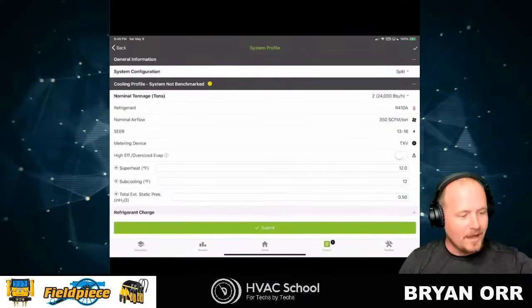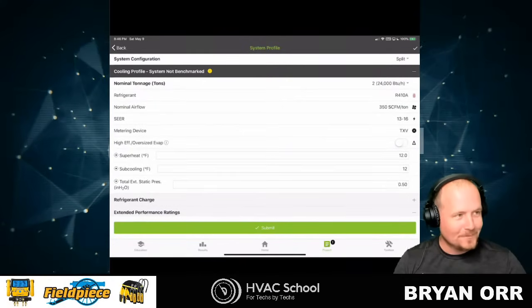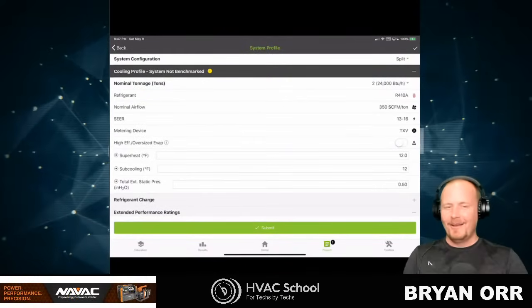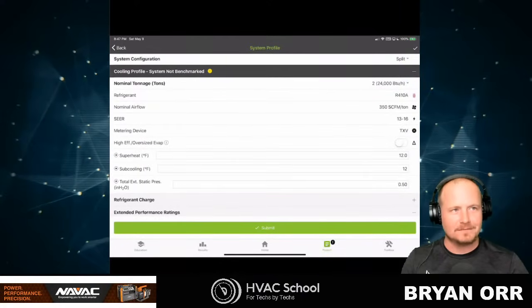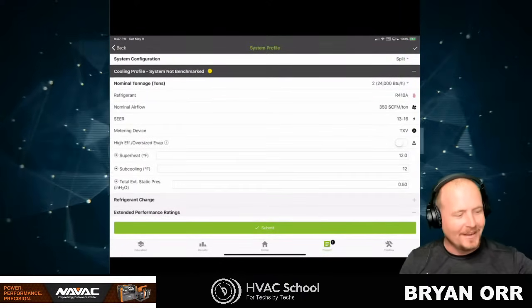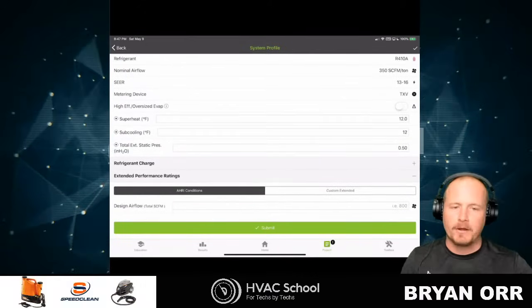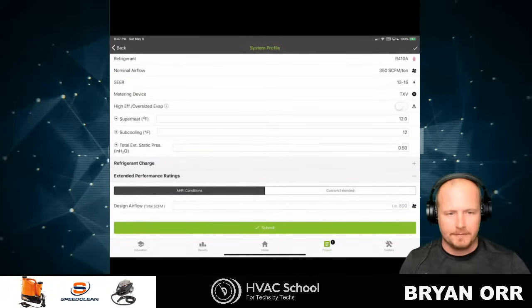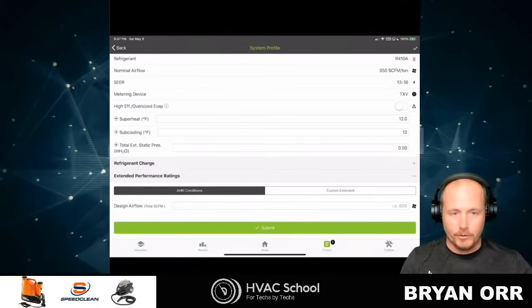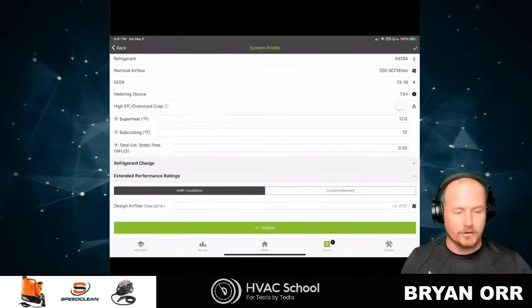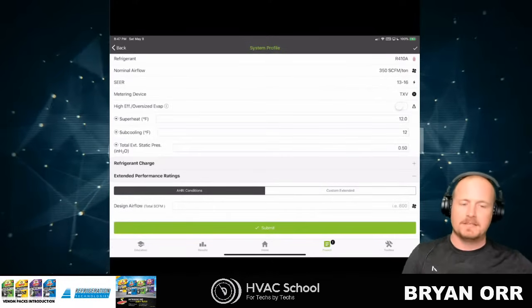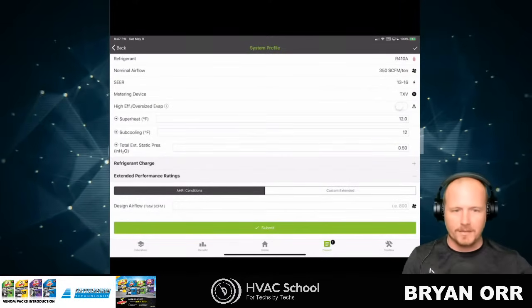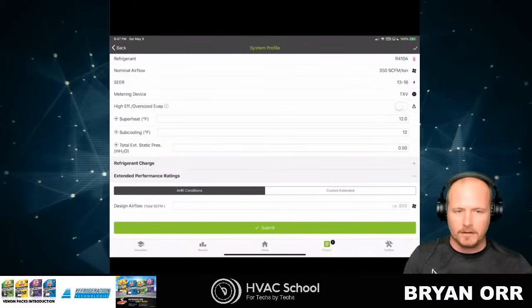Okay, keep going. Just like you started this project blank, and we can go there too if you want. You've probably started a lot of projects blank anymore. So you enter superheat on a TXV, you're generally not going to edit that unless you know there's some reason that you need to. Subcooling, you're going to go based on what the manufacturer data plate says. If it's superheat on a fixed orifice, well, that's going to be a moving target depending on conditions.